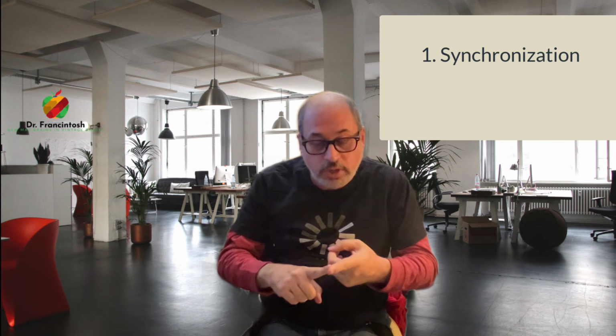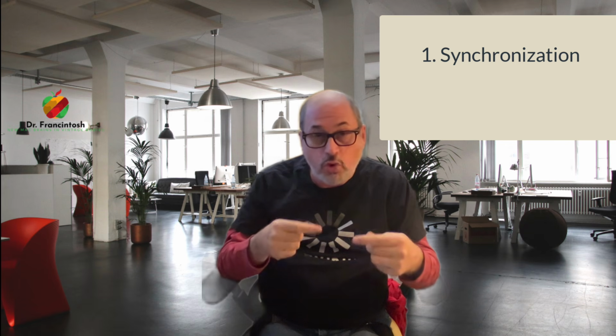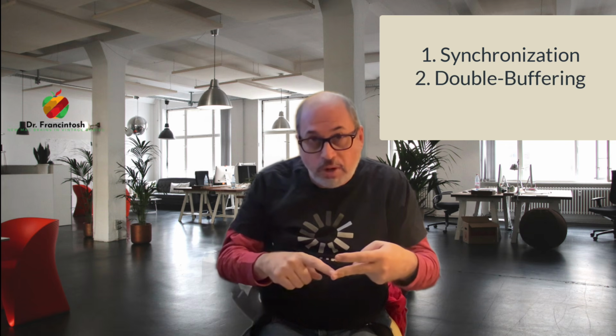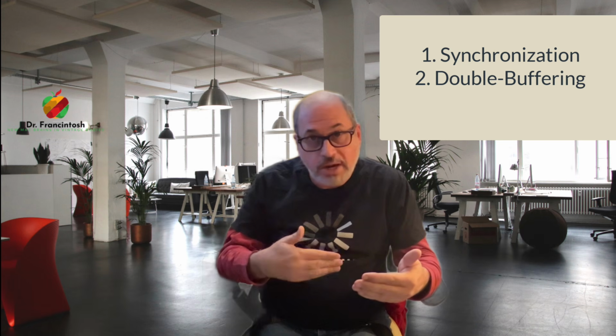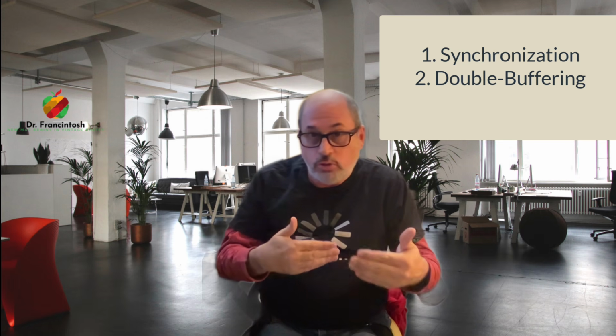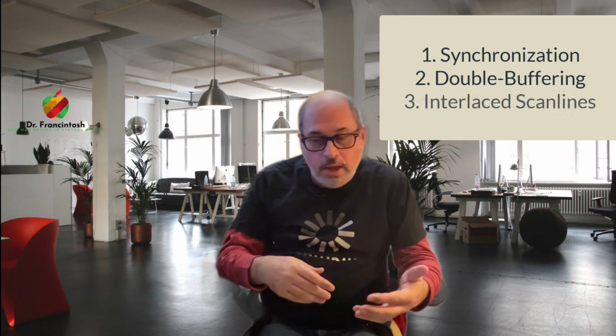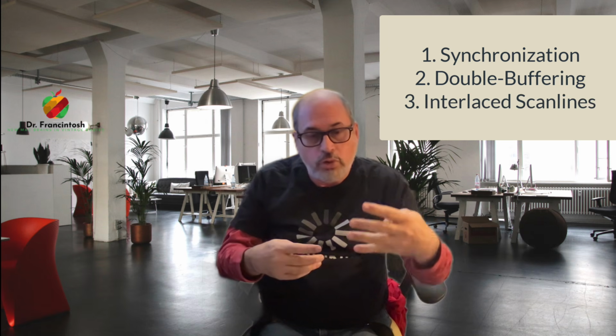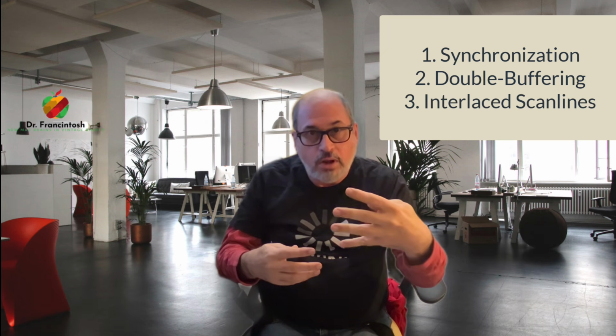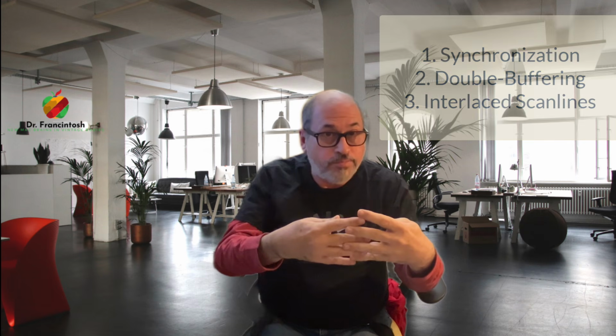So before we get started, what you're going to see is me sharing with you how to create the different graphics modes, 320 by 240, 640 by 480, and the challenges that I had as I went along and how I solved them. The three big solutions to the timing issues were synchronization, which we'll talk about as being synchronizing Core 0 with Core 1, double buffering, the ability to use a foreground and background bit plane so that we aren't drawing on the memory at the same time as we're displaying it. And finally, interlaced graphics, where we're showing half the scan lines on the even frame and the other half on the odd frame. So let's get started.